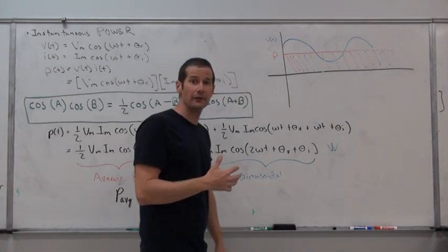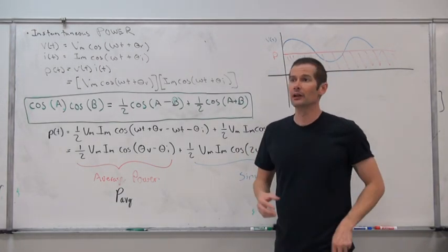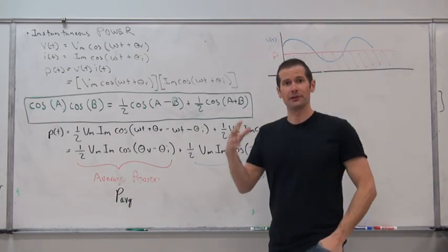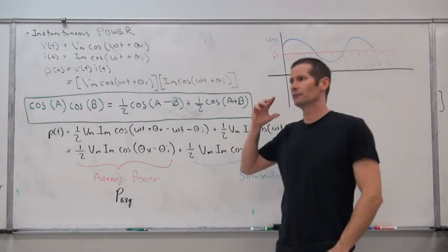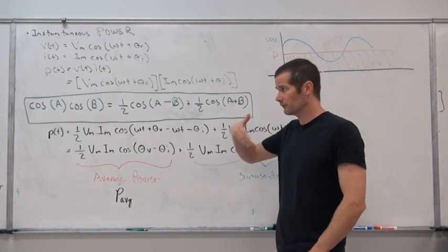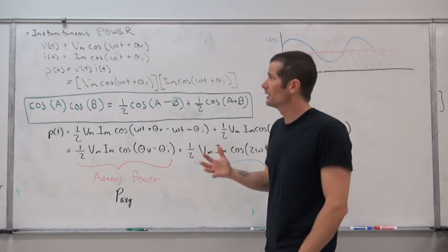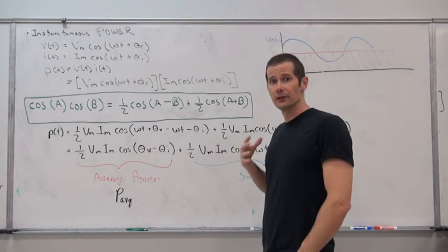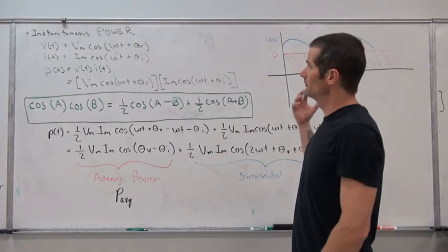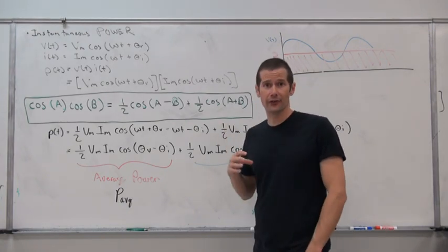All right, guys, now that we have gone through a review of phasor arithmetic and sinusoidal steady-state analysis, in which we took the original circuit, looked at the sinusoid's angular frequency, converted all the capacitors and inductors into their impedance equivalents, and then solved the circuit essentially with DC methods, we're now ready to talk about power within a circuit and definitely an AC system.